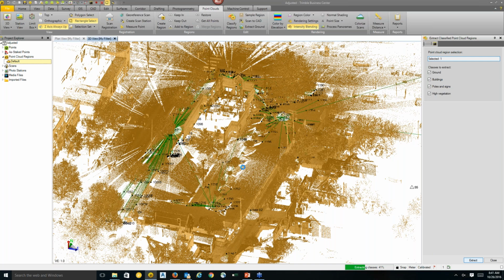If you are using a high-speed scanner today, it's not going to be as automatic as in RealWorks when you do plane-based registration. Essentially, you have a concept of reference and moving. So if you have 120 scans, you would click on that and register pairs 119 times. That might not be feasible for you if you're using a high-speed scanner.